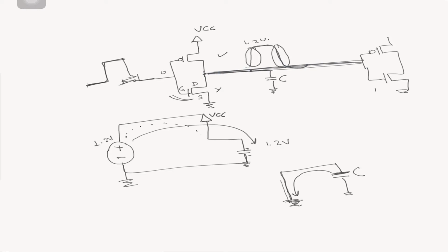And what I ignored at that time was that there is also capacitance of this node. Let's say this was C1, and there's also capacitance of this node, which is like a gate connected to these MOSes. Let's say capacitance 2. Let's call this CL, which is a load capacitance.